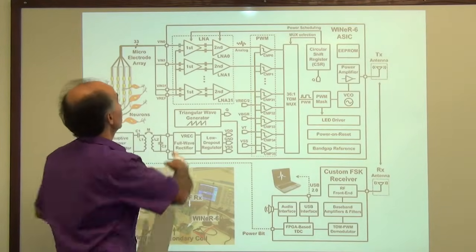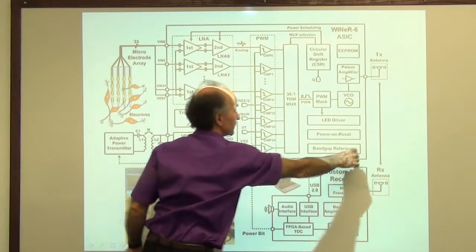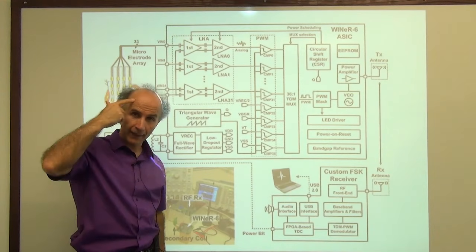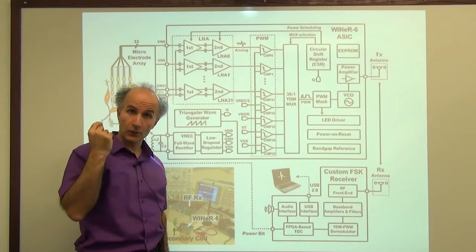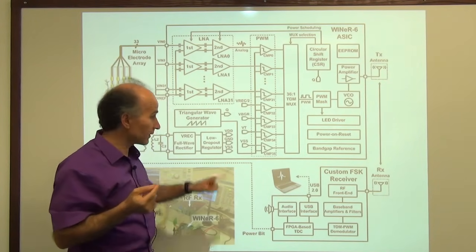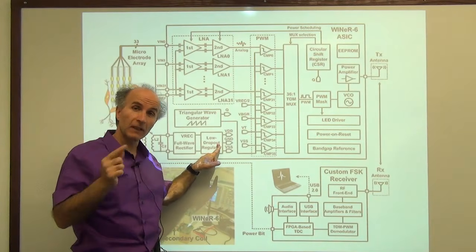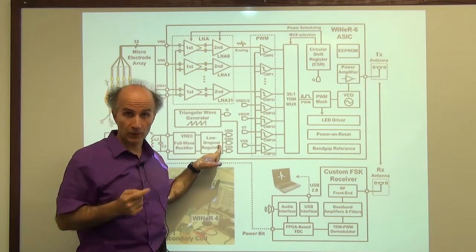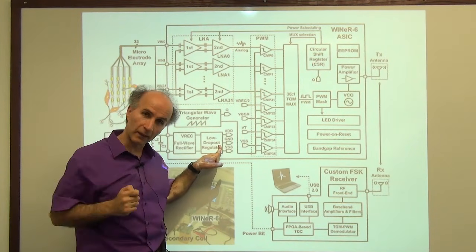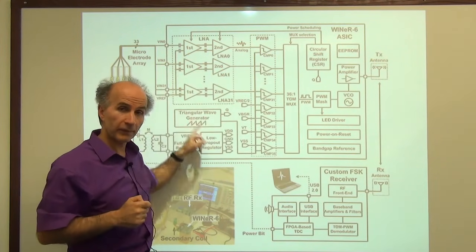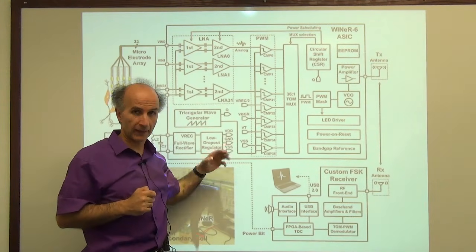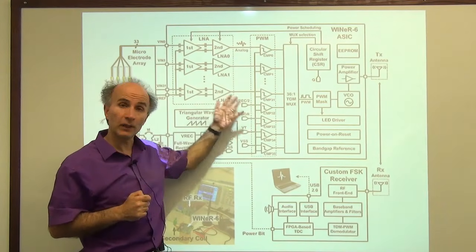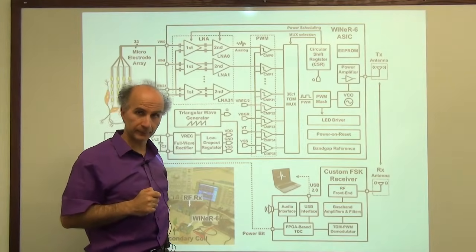And the hope is that all of the circuitry here in this big box can be on a little device that we can attach to the brain. That device has to consume very little power so that this chip doesn't heat up. If it heats up, it's going to burn the tissue on the patient's brain. So that's one problem. And of course, the battery will run out quickly. So the challenge here is to design all of this for very low power consumption. And that's an interesting application of electronics. There's a great deal of research going on today on these types of circuits.